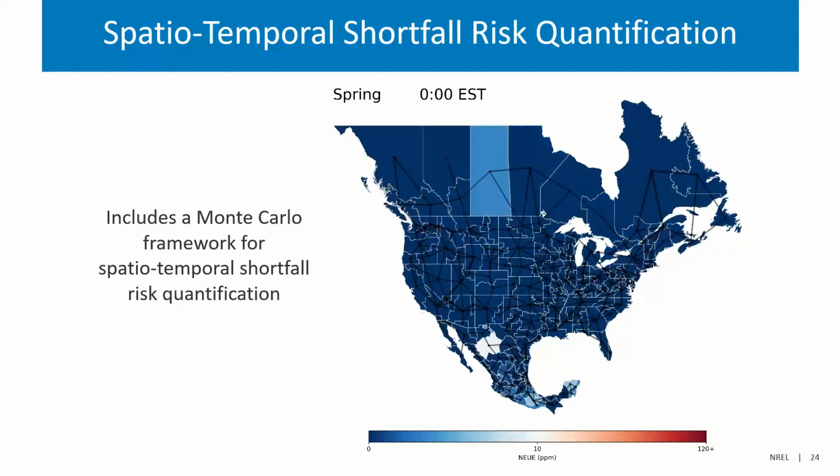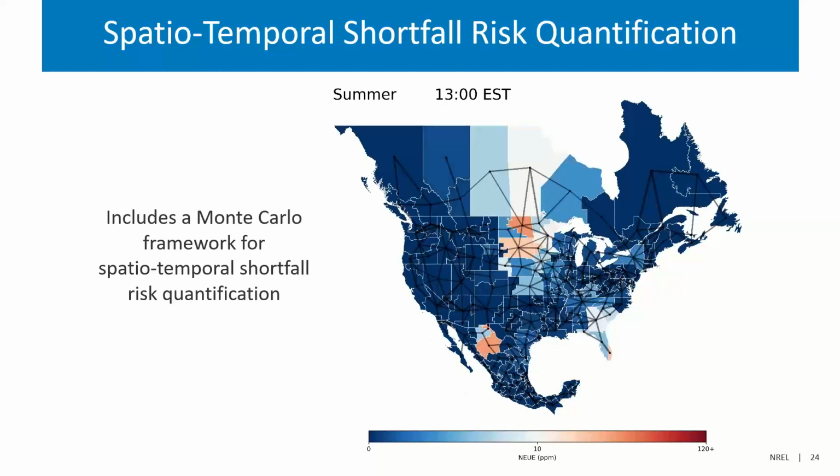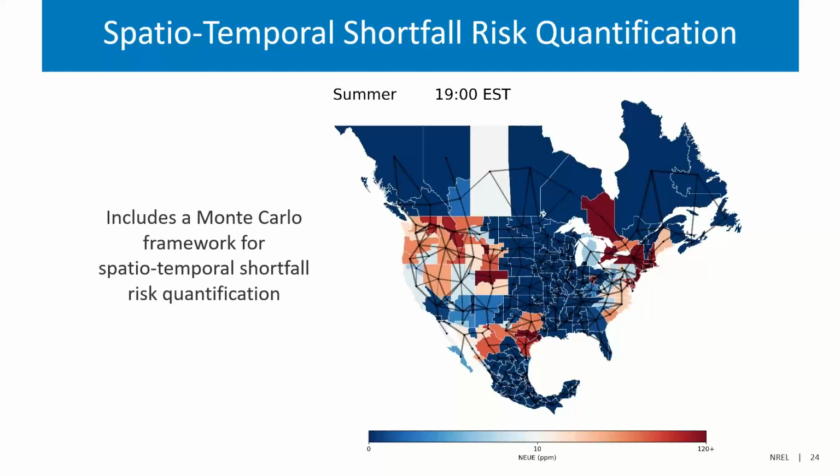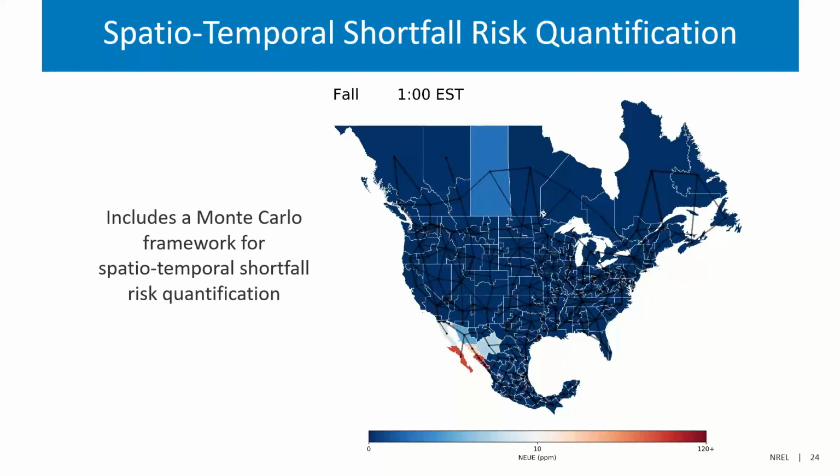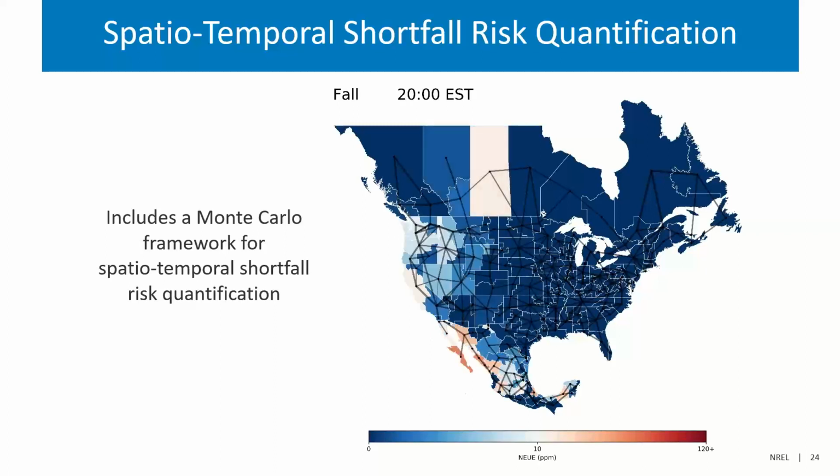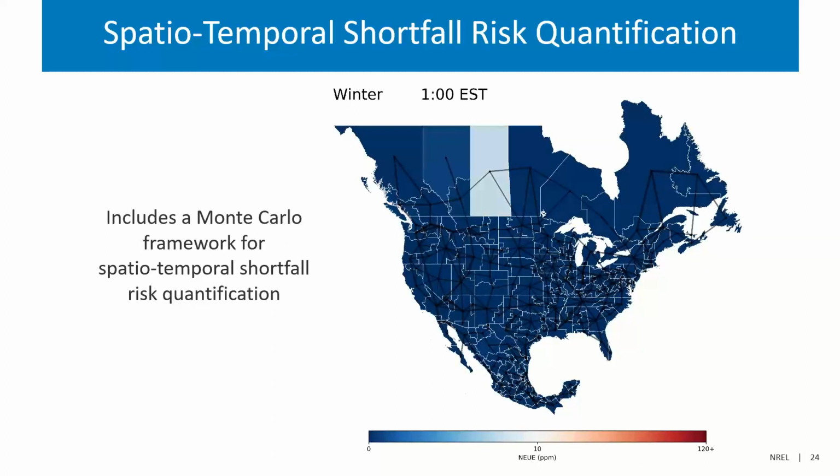However, the probabilistic method looks at your charging and discharging. If charging a bunch of storage units is causing stress during specific time periods, which are not the hours that you're considering in the approximation-based method, then that shows a more realistic capacity credit versus when you're only looking at a certain number of hours.